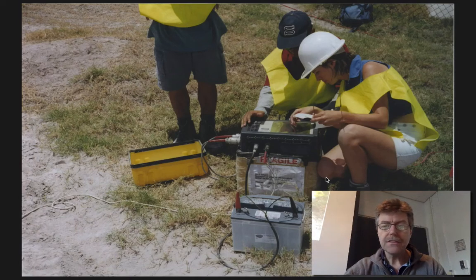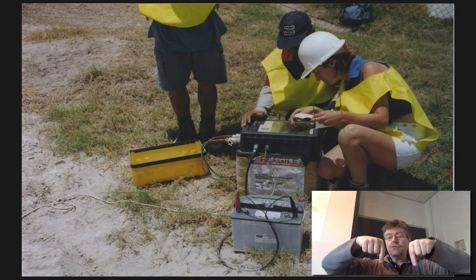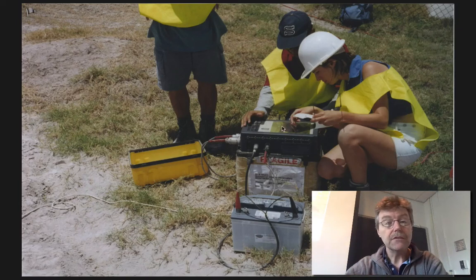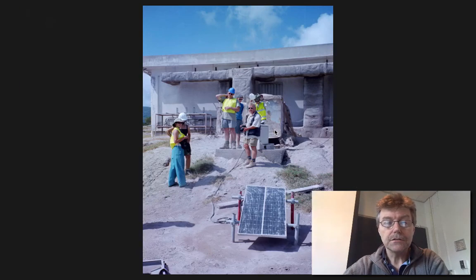And I think that this is an electrical resistivity survey. A battery, cables that go out to put energy into the ground, measure the voltage difference between two electrodes between them, change the configuration of the electrodes, and you get one reading from a voltmeter to tell you what the resistivity is at these intermediate positions.